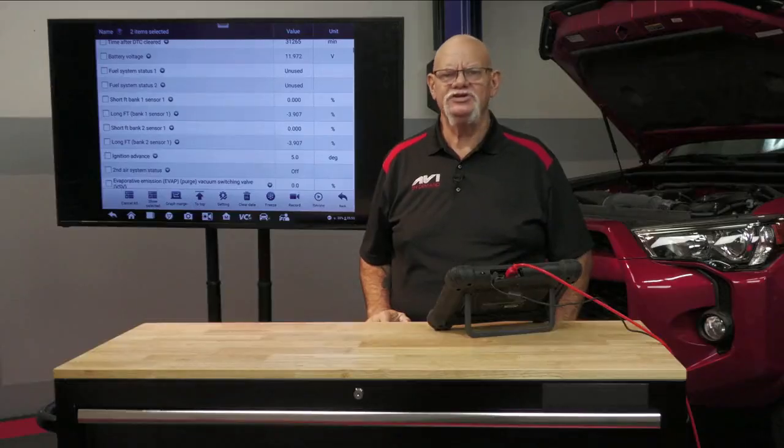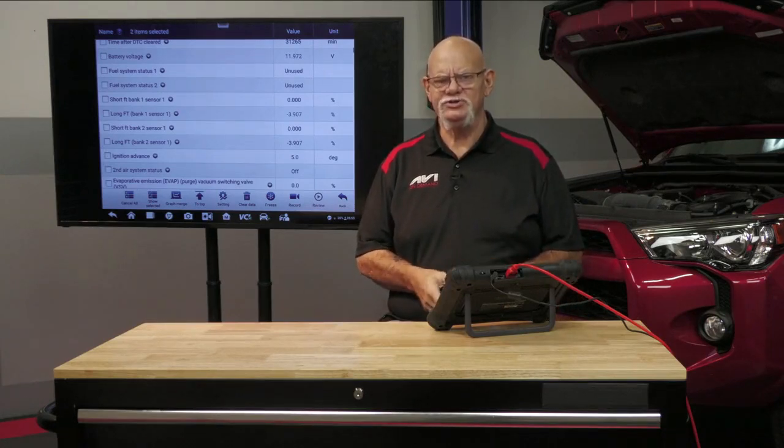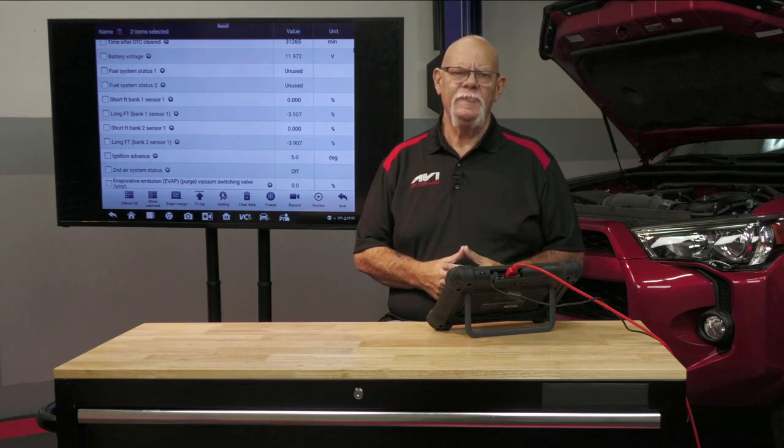You either have a breathing problem on that bank, not the bank that went positive, or you could have a variable cam timing problem, which is a breathing problem, or you could have a clogged converter that just affects that bank. So whatever testing you have in your arsenal for testing the catalytic converter, pressure test, temperature test, utilize that to see if it's a clogged converter.